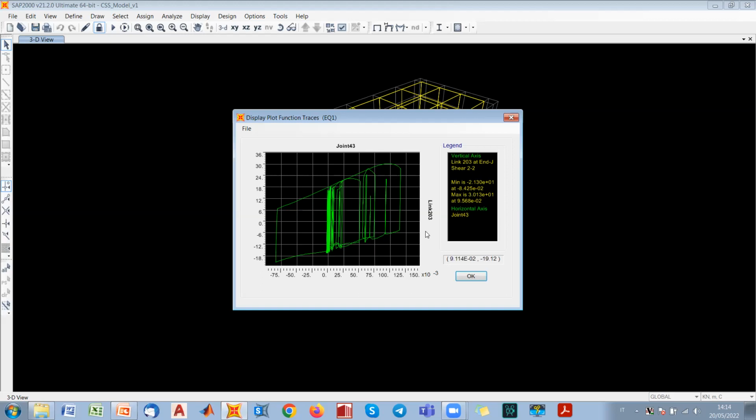You see that this is quite different with respect to what we are expecting for the theoretical behavior of curved surface sliders. You see that there are actually deformations, let's say, of these branches with respect to the straight lines that we were expecting. And these are attributed to the variation of vertical load, mainly because this is the response of the single device, and the single device considered here is actually at the corner of the building. So this is the location where we have the maximum influence of the overturning effect induced by the motion of all the floors.